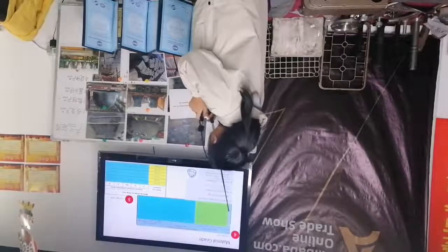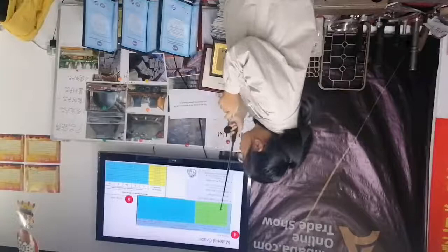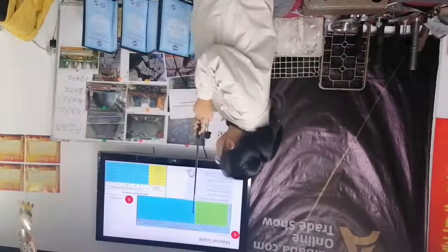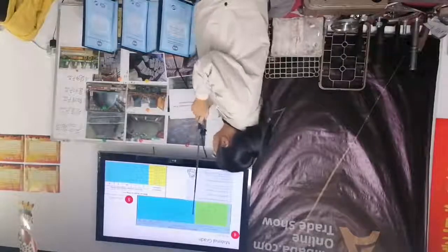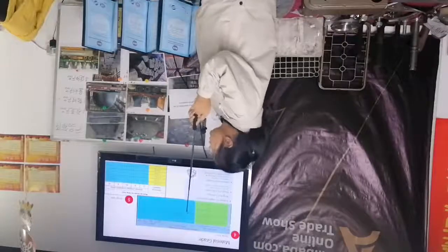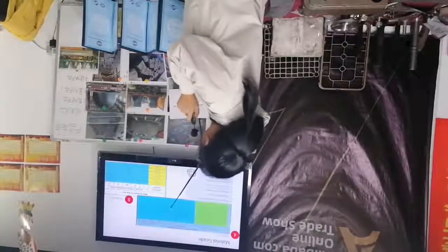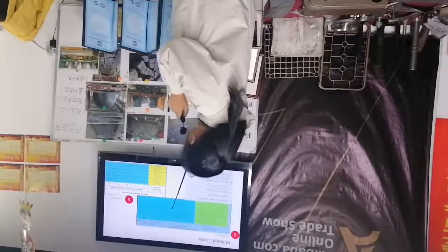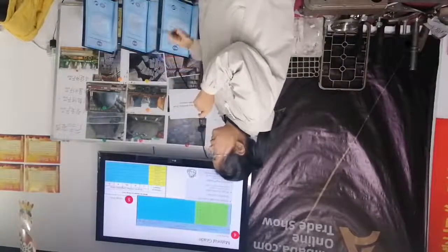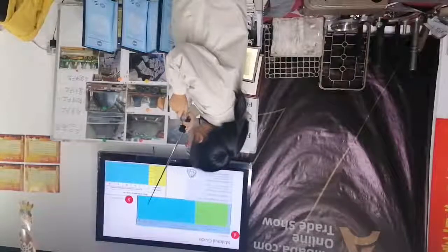For composition, for example, QT 527, the carbon is 3.4 to 3.8, the silicon is 2.0 to 2.9%, the magnesium is 0.03 to 0.1%, and the iron is balanced.